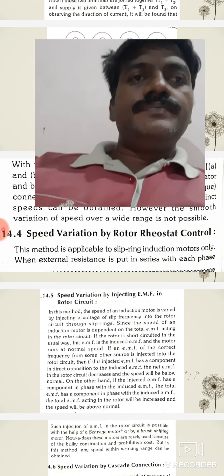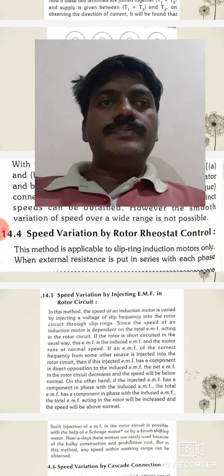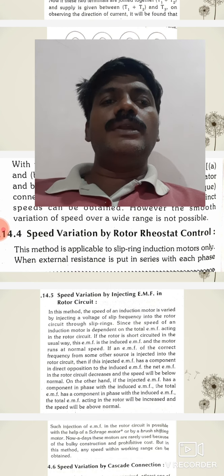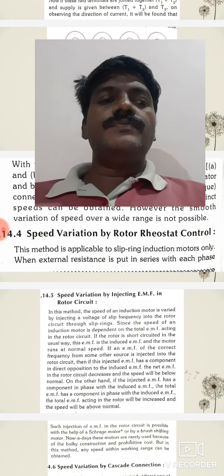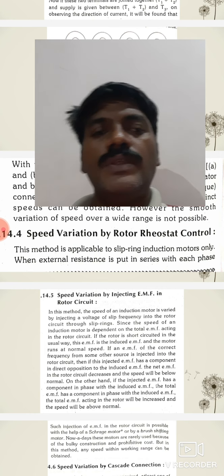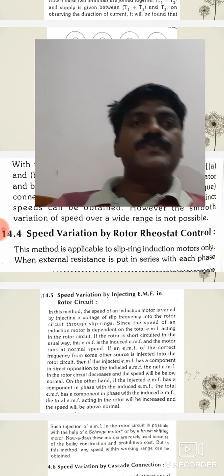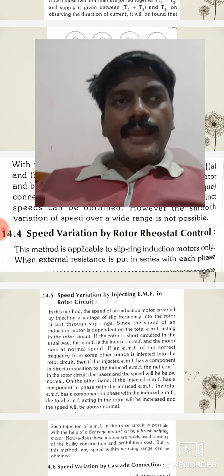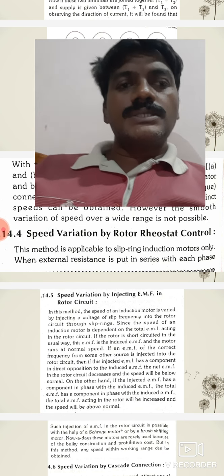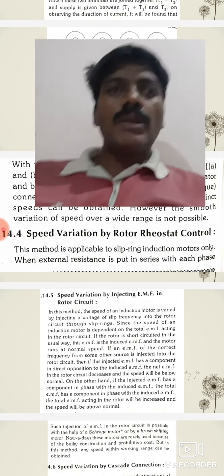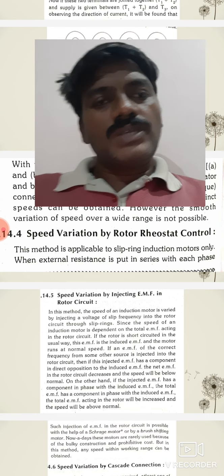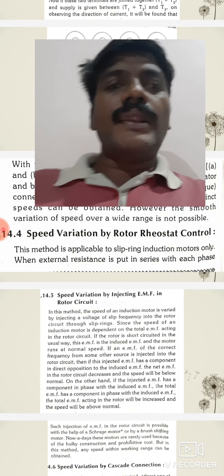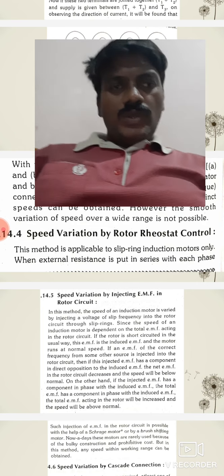The method is applicable to the slip ring induction motor only. When external resistance is put in series with the phase of the rotor circuit, the rotor copper loss increases, and the slip is given by the equation: slip is equal to rotor copper loss by rotor input.